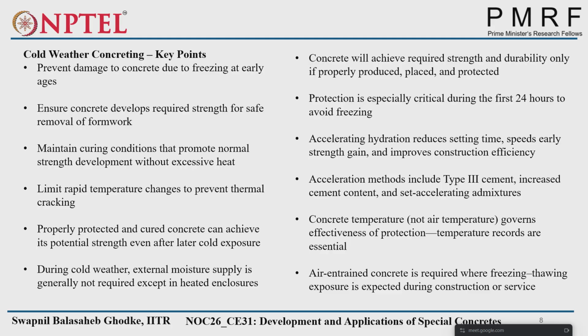And only concrete temperature, not air temperature, governs the effectiveness of protection. So in any type of cold weather concreting or hot weather concreting, you always have to note down the temperature of each material constituent, the temperature of the concrete after preparation, and the temperature of the weather.